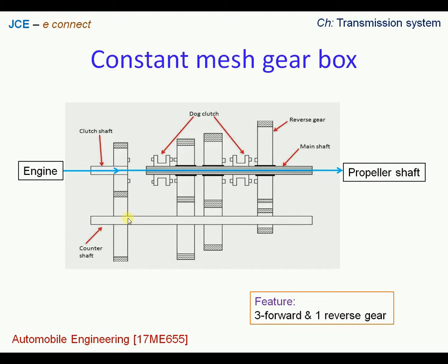However, the rest of the wheels are also in rotation, but since they are mounted on the bearings and there is no clutch dog being engaged, the right one, with any of these gear wheels, there is no power transmission from these gear wheels to the main shaft.